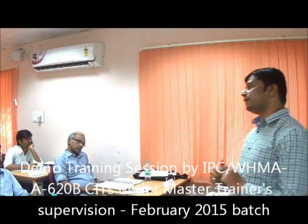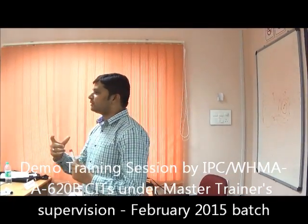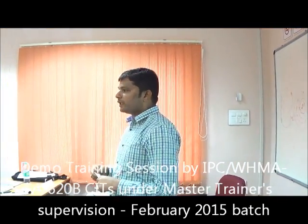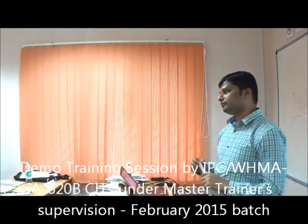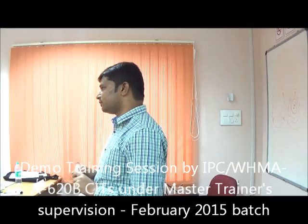And then we have the other additional method where we use retention tools. As the name tells, it verifies whether the inserted contact has been retained in position or not. So we need to apply some pressure and make sure the contact which is inserted is retained in its position. I just thought to give some brief introduction on this connectorization. Do you have any doubts?